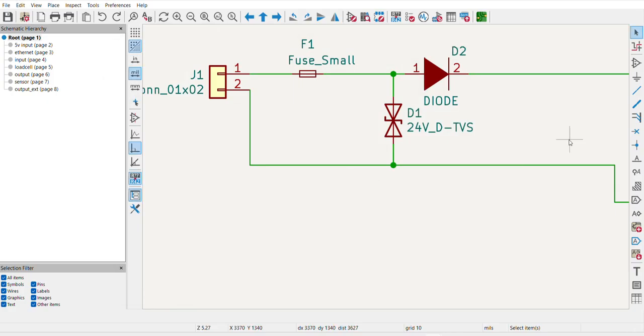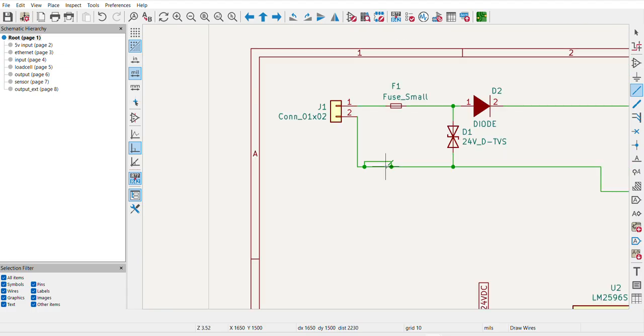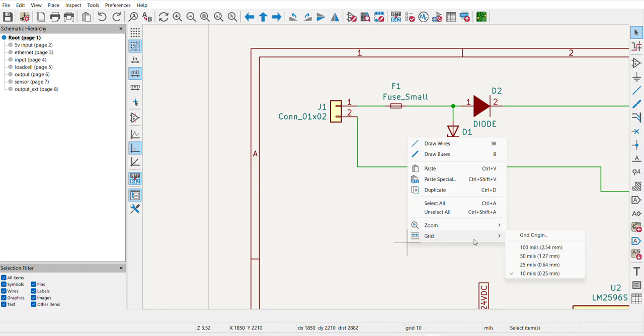So now I am editing again. You can see I am adding the wire tool; I am pressing W. Now I am able to seat the lines. So when we are upgrading from some older platform to a new upgraded one, we may face this kind of grid overlapping issue because our tool grid is not set properly. So we can adjust the grids and get the proper data.